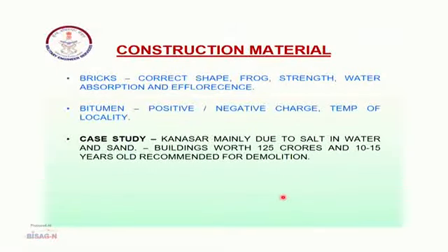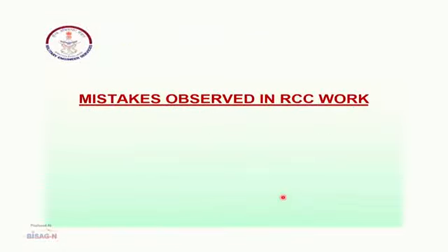Coming to other, not basic raw materials, but which also do not have much supervision at the workshop, that is the bricks. So, its shape, frog, strength, water absorption and efflorescence are very important. Mistakes observed in RCC work.